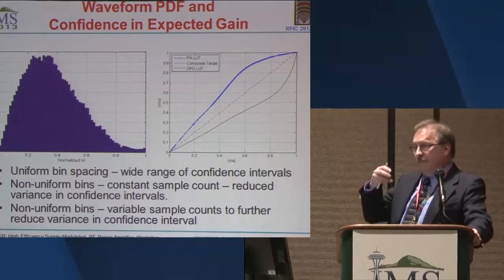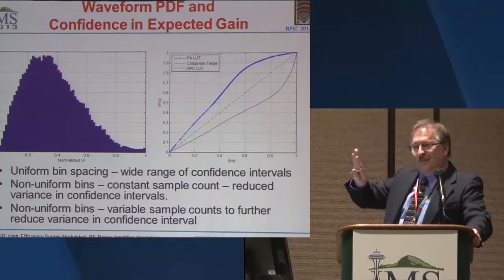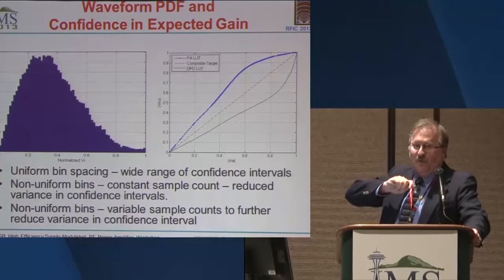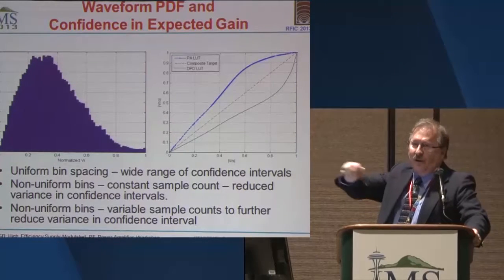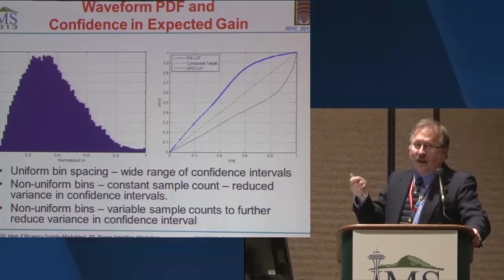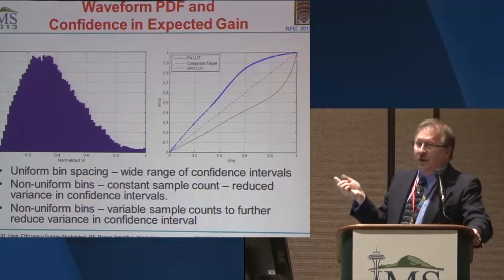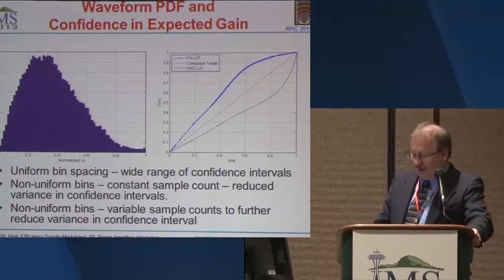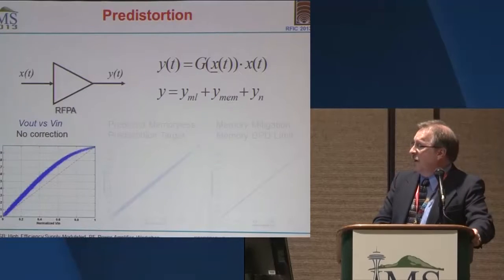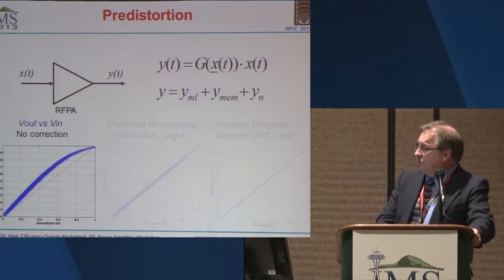And by building the exact crest enhancement to apply to the PA before it gets into the DAC, and then run that signal all the way through the RF chain, it hits the PA, it goes through this compression, and it winds up on that red line in a very clean way, which we'll see in this slide.